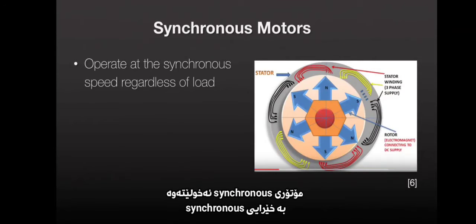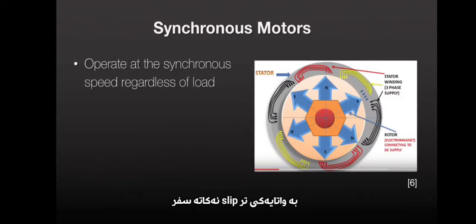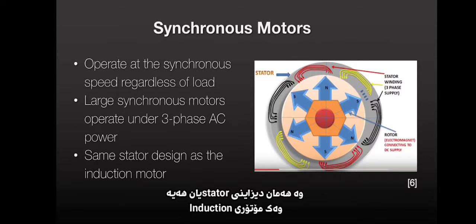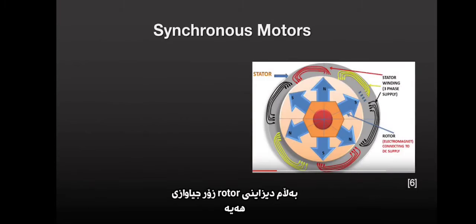Synchronous motors rotate at the synchronous speed, regardless of the load on the motor. In other words, the slip is 0. Large synchronous motors operate under 3-phase AC power. They have the same stator design as the basic AC induction motor. However, the rotor design is fundamentally different.